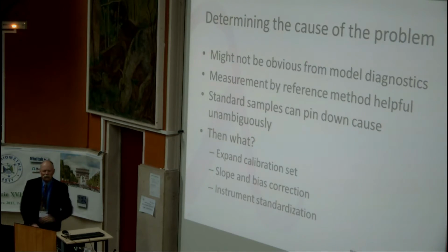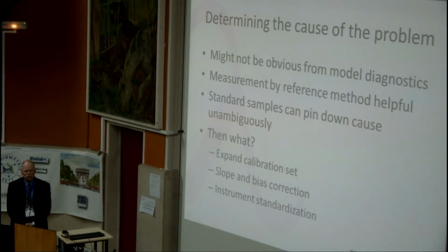The measurement by reference method is extremely helpful. Standard samples can pin down the cause unambiguously. But then what? You need to either expand the calibration set, do a slope and bias correction, or do some type of instrument standardization.